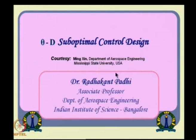The whole concept of theta-D control design tries to address one issue of SDRE, that online solution of the Riccati equation is problematic. In other words, if the dimension gets bigger and bigger, online solution of the Riccati equation is a concern. You cannot really do that online. So how do you circumvent that? How do you propose a different technique which will address roughly the same problem, but will not have that difficulty?